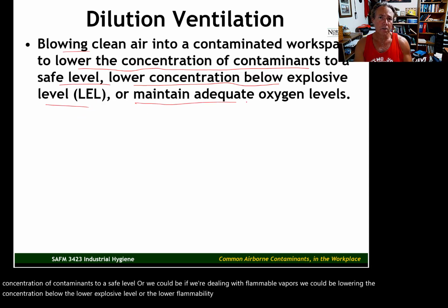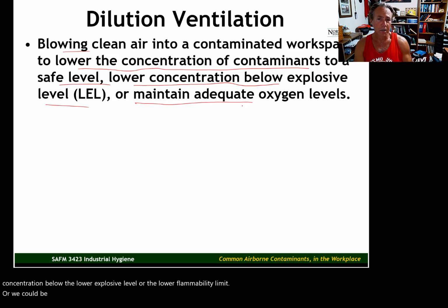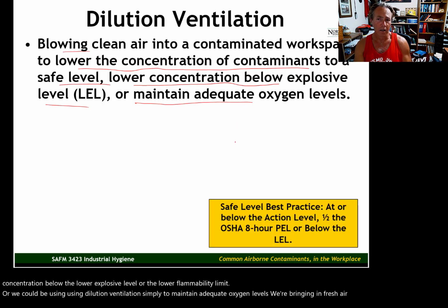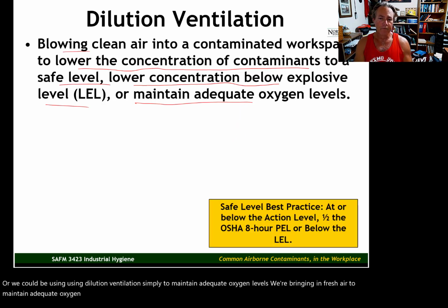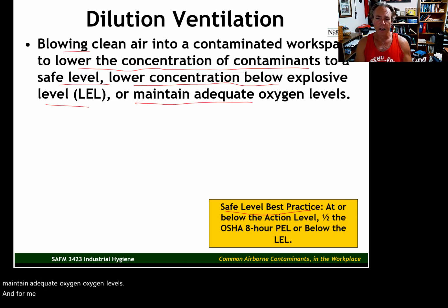Or we could be using dilution ventilation simply to maintain adequate oxygen levels. We're bringing in fresh air to maintain adequate oxygen levels. Again, for me, the safe level best practice, like I mentioned before, is at the action level, one half the OSHA PEL, or below the lower explosive limit.